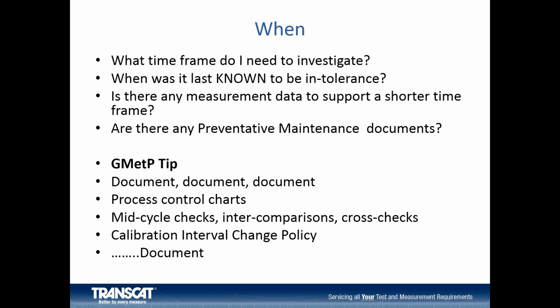Here at Transcat, we use SPRTs as temperature devices. On a weekly basis, we monitor these, and we take a 0-point reading. We record the resistance and the temperature readout of these. Every week we monitor these, and if they start to drift to a certain point, we know that we should stop using it and send it in for cal. This limits our exposure to out-of-tolerance conditions.